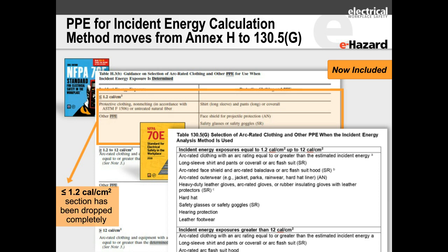So functionally, there's really no change here, but some people will take this and make a mistake of putting people, say, in a power plant in non-flame resistant clothing and even letting them wear polyester, when if they ever have to put on an arc flash suit, they're going to have to take off their clothing, put on something that's non-melting, or put on the arc flash suit naked. So it's not really practical, so do be careful that you don't misinterpret something.